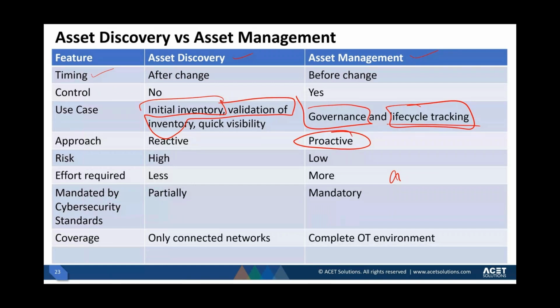In some cases, if you already have an instrument management system installed on your network, which is communicating with the field devices, let's say on HART or other fieldbuses, you may be able to connect with that instrument management system and get the inventory and other parameters.